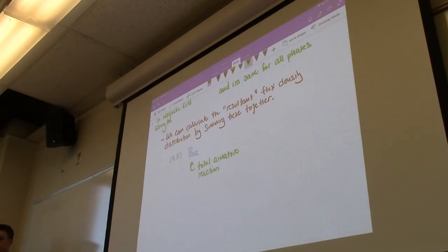We talked about the effect of the field winding on the stator winding, and now we're doing the armature reaction. That's going to be equal to K1 times IA e to the j0 plus IB e to the j 2 pi over 3 plus IC e to the j 4 pi over 3.